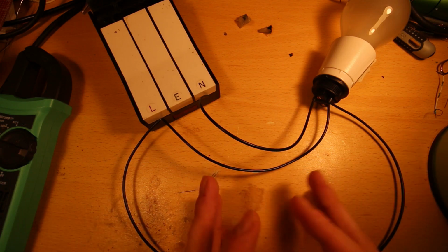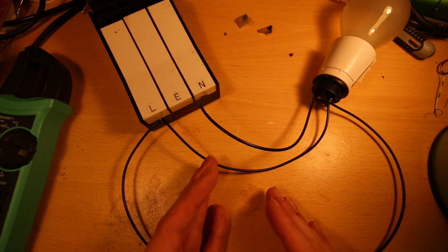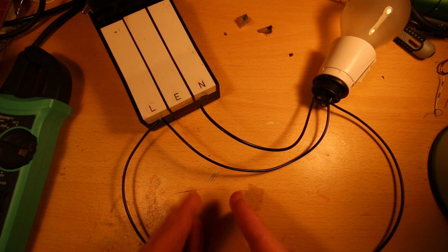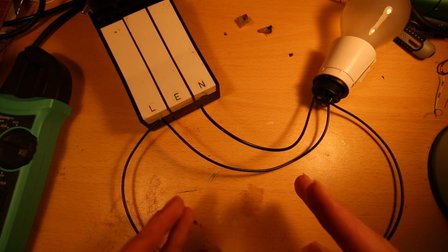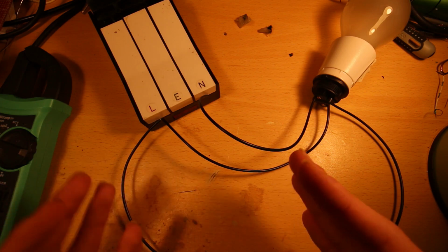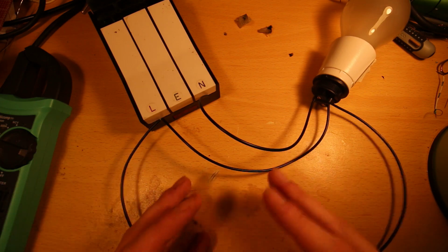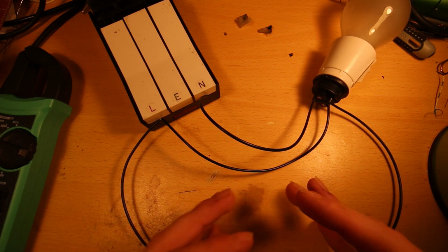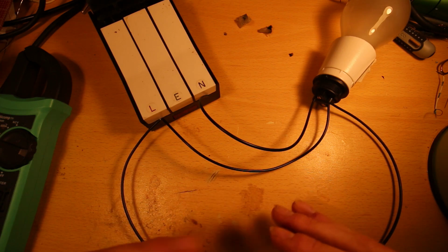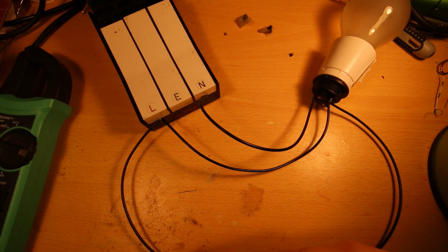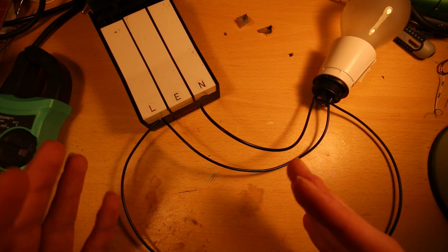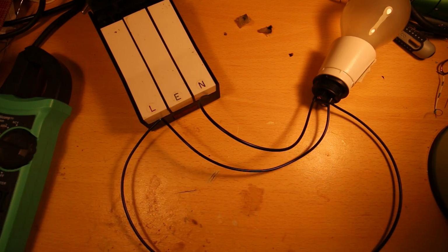But sometimes we do have to be mindful of that. For example, in the high voltage, as I showed, it will conduct through the air. So we have to be mindful that it can conduct through the air, and we have to make sure to design things around that so that it doesn't cause problems, and that the resistance is high enough that the current leakage through those paths is minimised to a point where it's not a problem.